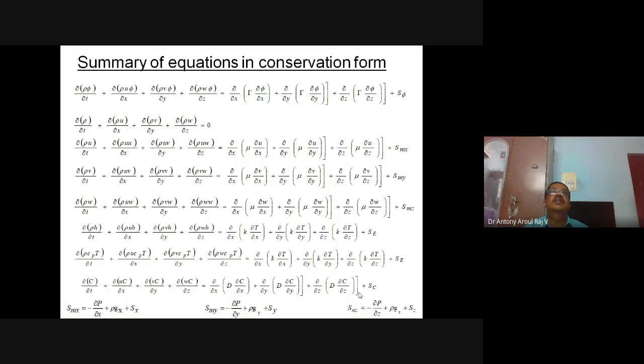But if you are going for energy simulation, you will mostly have one equation, the energy equation only. Similarly, in an FEA analysis, a structural problem, you will mostly have force balance only, the momentum equation only. But in CFD you will have a number of overlapping physics. So the number of equations solved per node is going to be higher in CFD, which means you are going to have a memory problem. So you cannot go for solving by direct methods. Direct methods mean the inverse method and Cramer's rule.